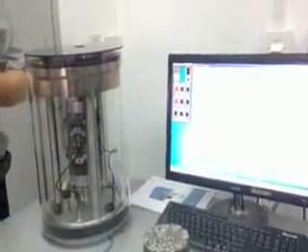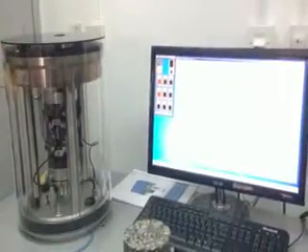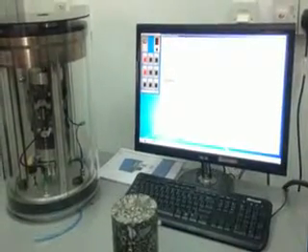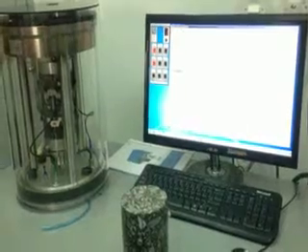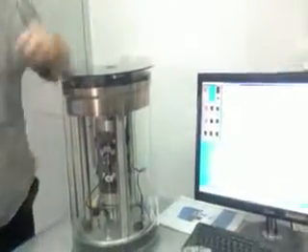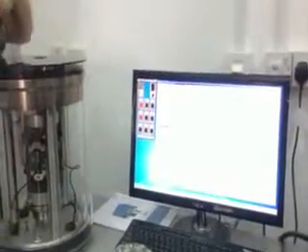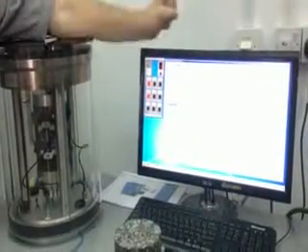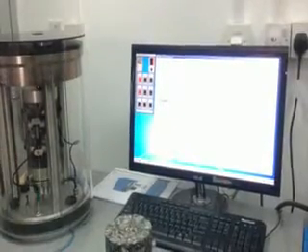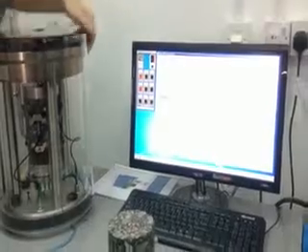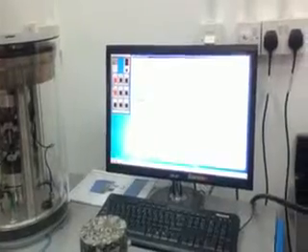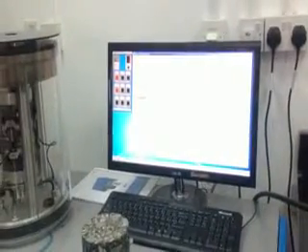So the standard says typically 5%; say if your deviator stress was 200 kPa, 5% of 200 is 10, so we'll use a 10 kPa seating load just to maintain contact on the top plate. If for some reason you want to do some non-standard testing, you can change these parameters. If you leave it ticked, then it just uses the standard. So now it has 5%. And also, you can adjust it.